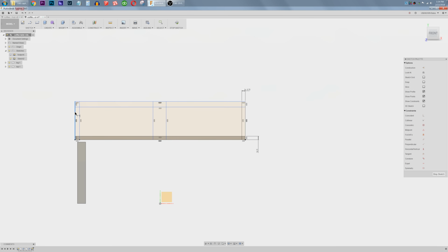So I can say this to this, Control V to paste, enter, same thing. This one to this one, Control V, whoops, that wasn't the right one. Control V to paste, D for dimension from here to here, Control V to paste. So that means if I edit this one to say, I don't know, 1, every one of the other ones will edit as well. Control Z to back up.